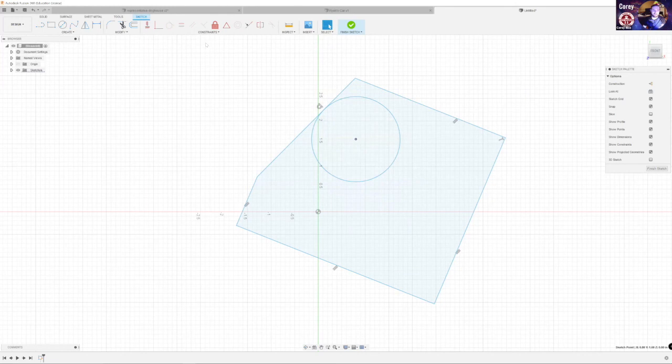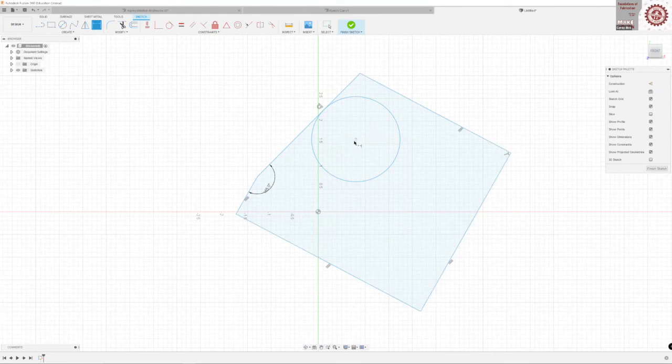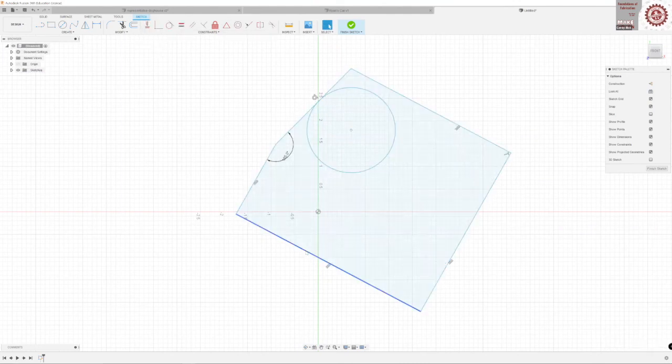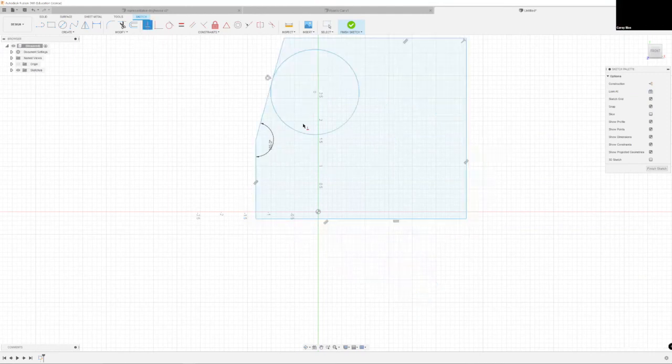So you can not only specify relationships like that, but you can also specify dimensions. And so the dimension tool is another one that's really helpful, where I can say that this and this should be, let's do 180 minus 15. So you can set up relationships like this, where now if I drag this around, you can see it's definitely changing how those two play. Or it's wigging me out, this isn't flat. We can say that this line should be horizontal, right?